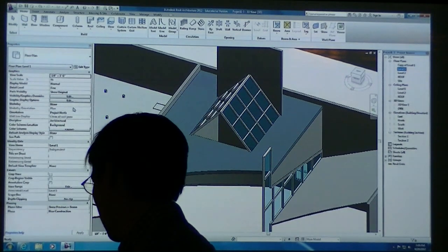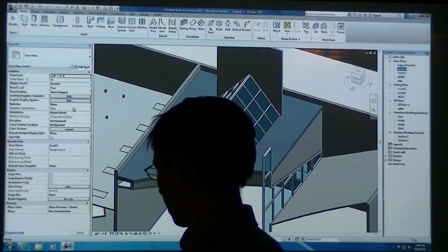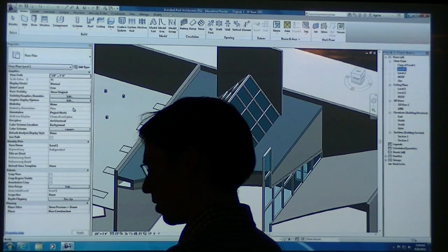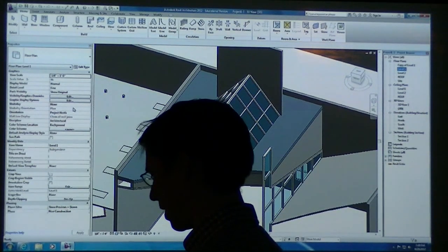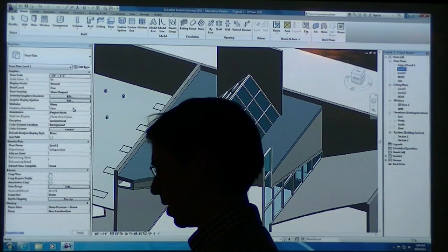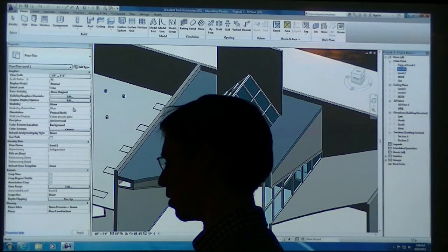And so a lot of times what I do for joining your floor with the other one is I extend it out, let's say another tread. There might be an option for that. And then I'll make it extend out and then turn, and then I make the other one butt into it. You'll get a line there, but when you render it, you won't see it.